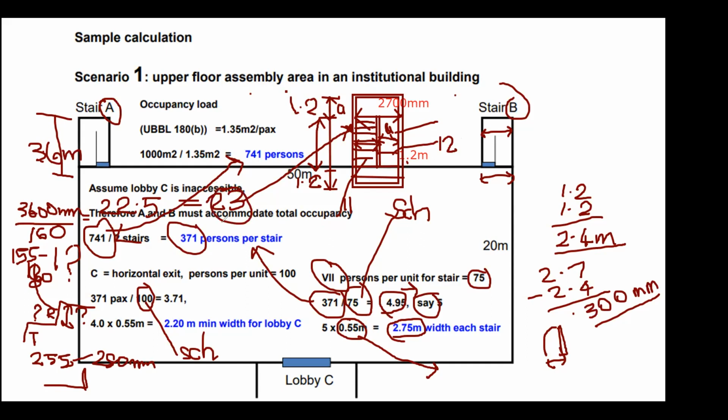Okay, now you know how to make the staircase. Now you know why the steps are very important: how to calculate how many steps per staircase, and what is the opening, the width of each staircase. For residential, the width here can be 1 meter clear. For commercial, for occupants, those who are so many, you can have 1.2 meters clear.